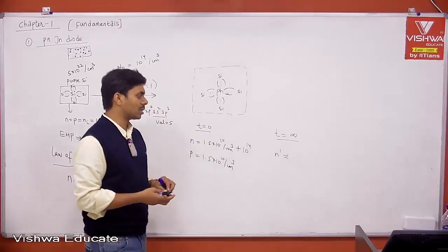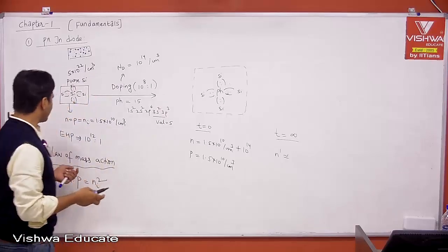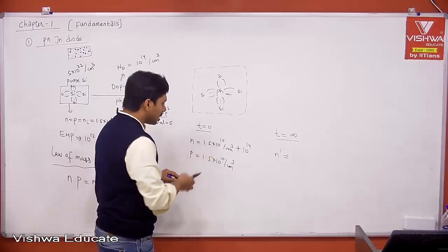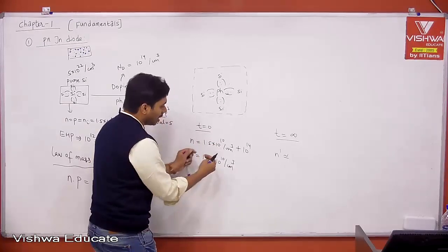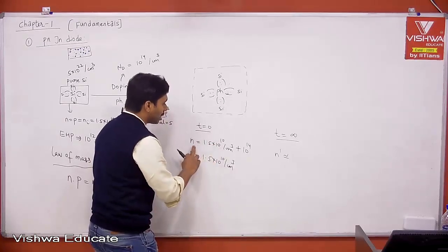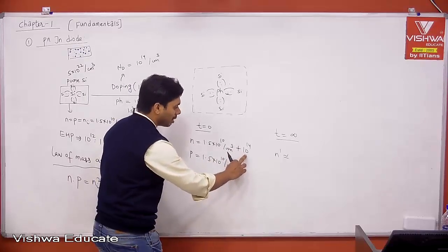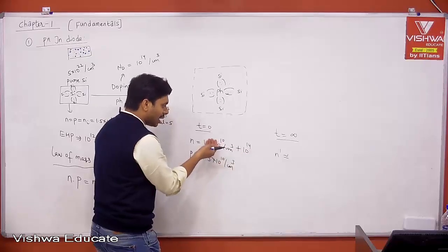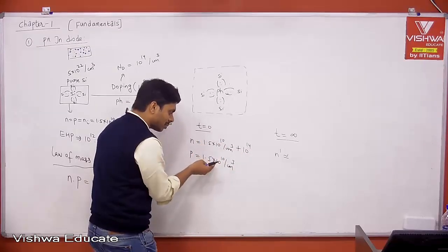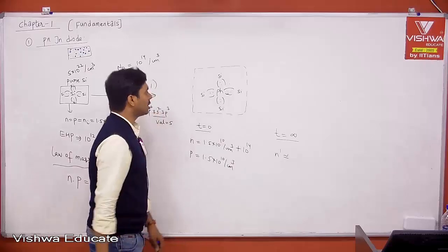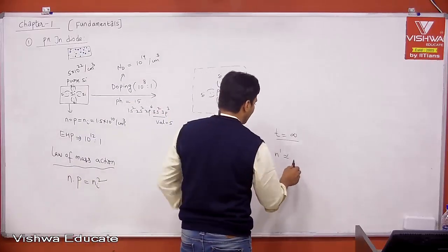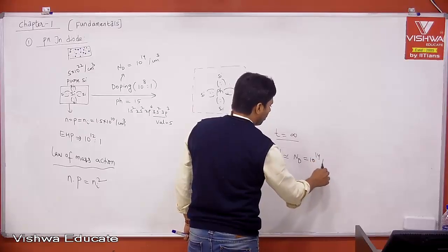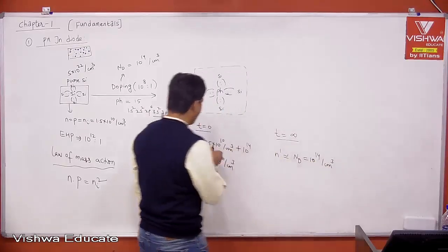Then what is that hole concentration or equilibrium hole concentration? That is what is explained by the law of mass action. Therefore, when I say N is equal to this, some of the electrons will come and recombine with the holes, your hole concentration will decrease, but your electron concentration will be approximately equal to 10 to the power 14, because 10 to the power 14 plus 10 to the power 10. I can say approximately 10 to the power 14, but some of the electrons from this portion are coming in and decreasing this part, but I can say N is approximately equal to your doping concentration. Let us say in this example, that is nothing but Nd, which is 10 to the power 14 per centimeter cube. We can ignore this part.